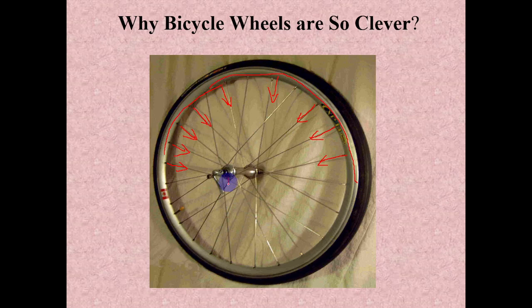Whatever load we are applying here, this load will be transferred to the ground through these spokes by tension. Even though it will create some compression, since all our spokes are in pre-tension, this tension is getting reduced. It's not going to reach zero or any compression at all.